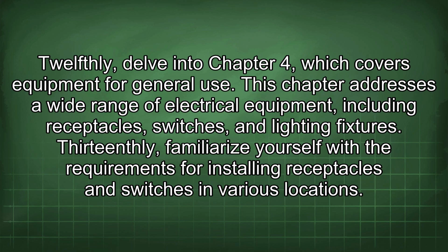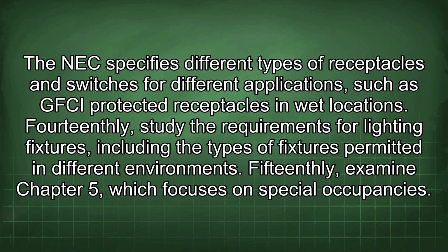13thly, familiarize yourself with the requirements for installing receptacles and switches in various locations. The NEC specifies different types of receptacles and switches for different applications, such as GFCI-protected receptacles in wet locations. 14thly, study the requirements for lighting fixtures, including the types of fixtures permitted in different environments. 15thly, examine Chapter 5, which focuses on special occupancies.